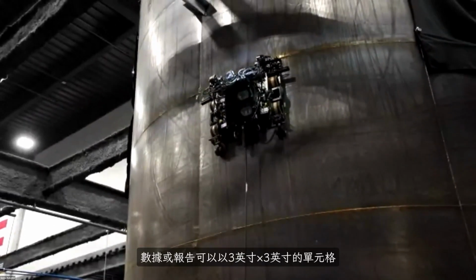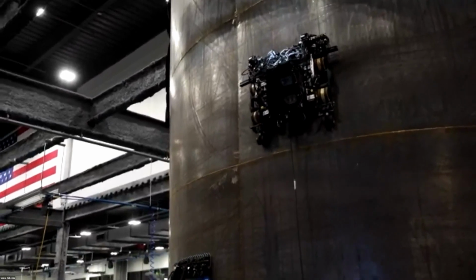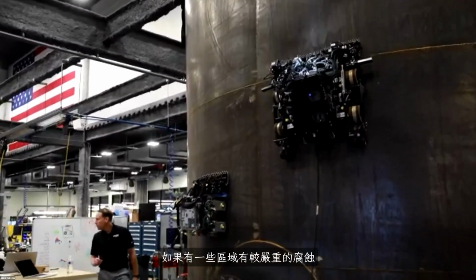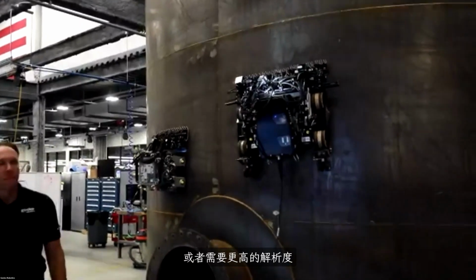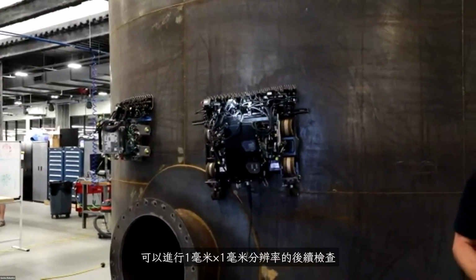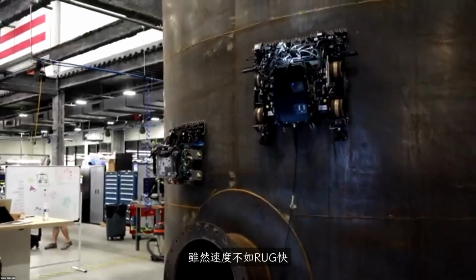The data or reports delivered can be done in a 3 inch by 3 inch bin or a 1 foot by 1 foot bin, showing the hot spots of the corrosions at the time of the inspection. Afterwards, if there's some areas of interest that have some pretty severe corrosion or something you'd like to really dive in deep on and get better fidelity on, we have a phased array robot similar to the one shown here that has a 1 millimeter by 1 millimeter resolution for follow-ups in those hotspots that are seen in that RUG data. So not nearly as quick.